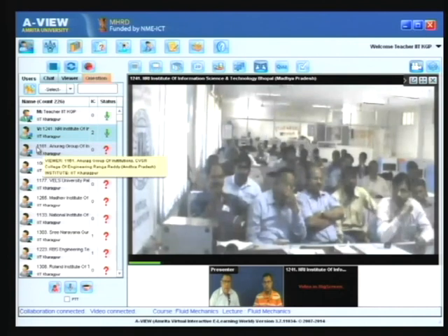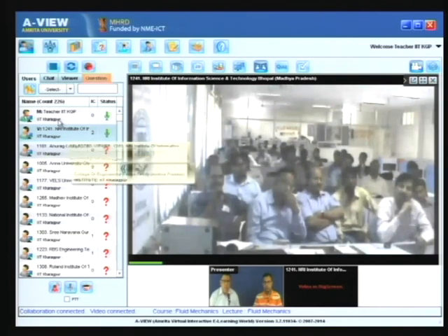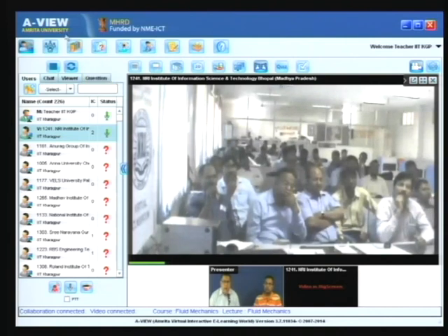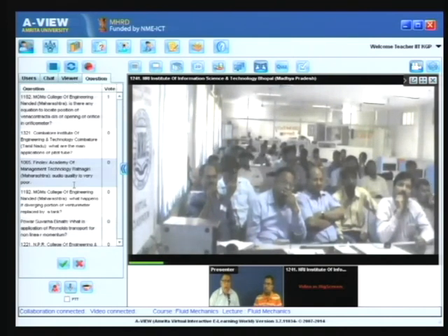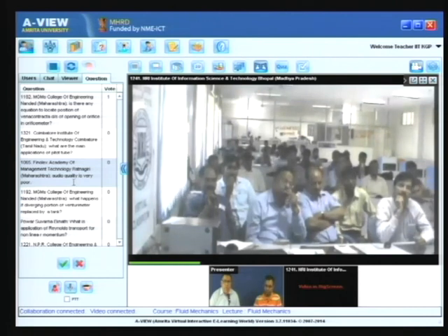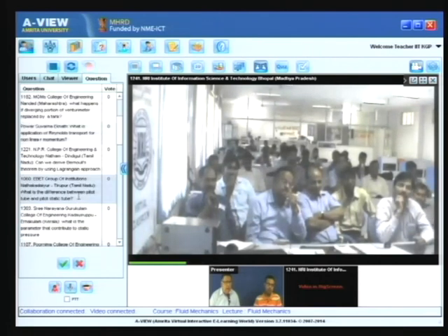See, what happens is that the pressure distribution is determined largely by the behavior of the flow in the core region of the duct, which behaves like an inviscid fluid. Now you have what is called a favorable pressure gradient in the converging duct. That is, in the flow direction, because the area is reducing, the velocity will increase and the pressure will decrease. So the pressure gradient dp/dx, if you say x is the streamwise direction, has a negative sign.